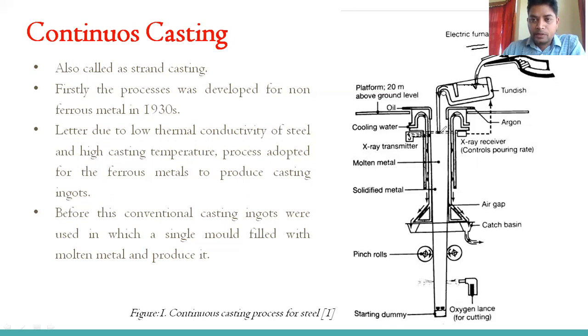Now, before filling this solidifying shell, we have to keep this dummy block closed, so that the molten material should not cross this one. So for that we are using this dummy block, which is in closed position. Now as we are filling, this molten material is coming through this and starts filling this one. As I said, this dummy block is closed, so it starts filling.